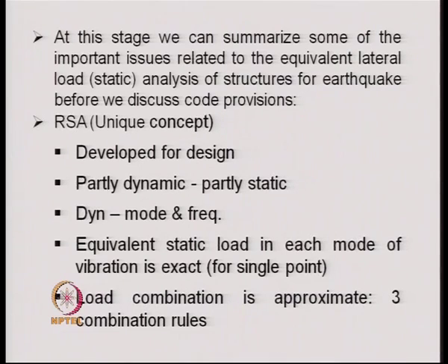This is partly dynamic and partly static, because the first part of the analysis requires the evaluation of the mode shapes and frequencies, which is the dynamic analysis of the structure.